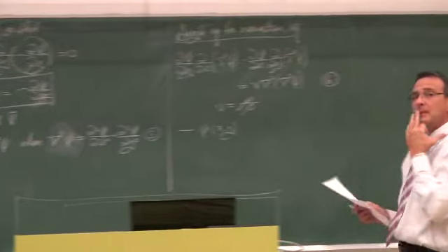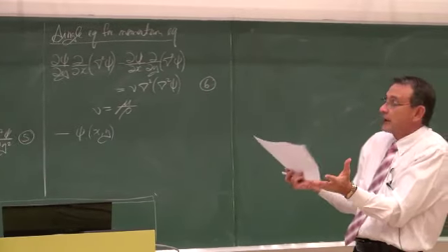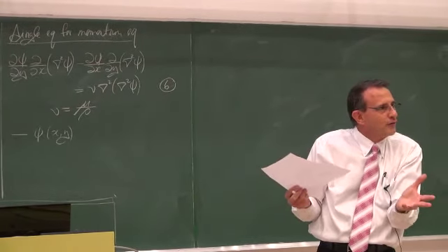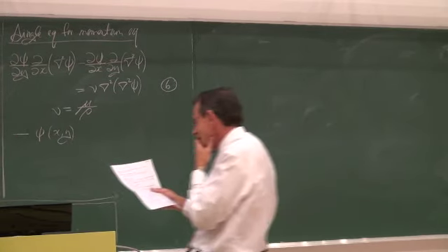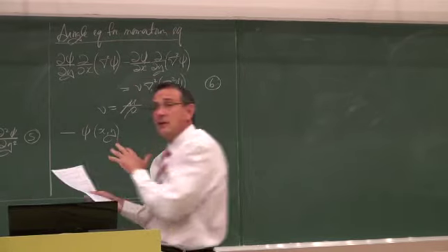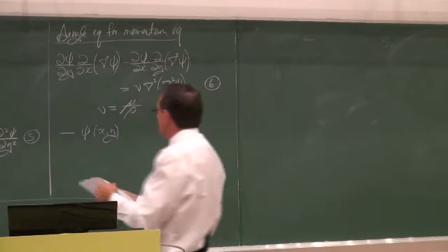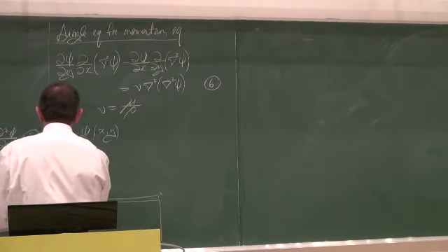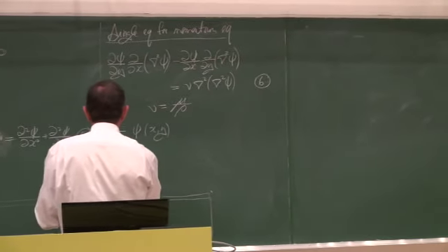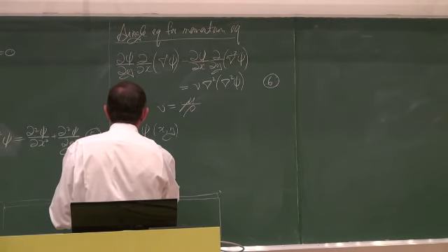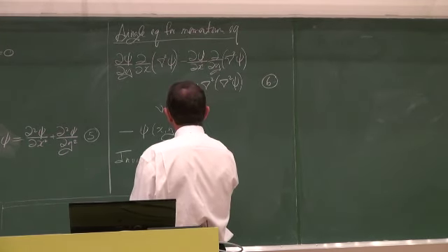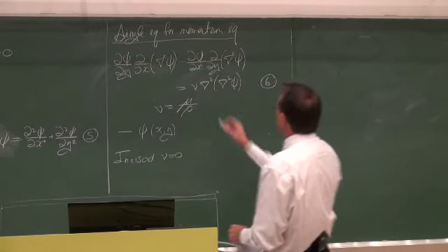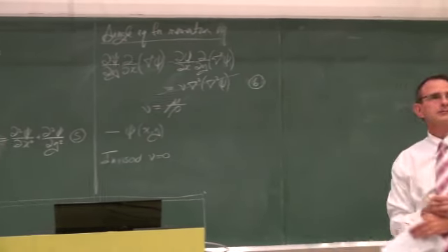Okay. Now again, this equation, we still don't have the analytical solution of it, unfortunately. So there's another Nobel Prize that can be won. So they made some more assumptions. They said, well, let's assume the flow is inviscid. So the viscosity is equal to 0. So this term disappears.